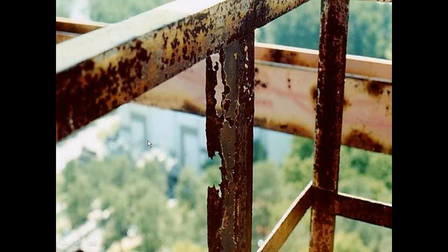There's corrosion caused by salts, just to give you an example to show that it is something worth considering. When this surface was tested, all this corrosion you see was caused by nitrates, a substance not often looked for, but it's pretty prevalent out there in the field. This corroded surface was a bridge painted 18 to 24 months before this photo was taken. It's a comparatively new coating. This one was caused primarily by chlorides, though some sulfates and some nitrates showed up.